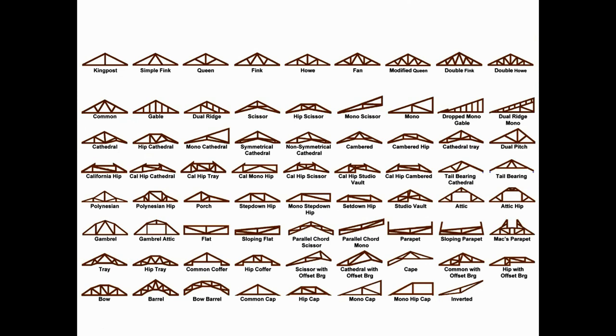And just to confuse you enormously, particularly when it comes to roofs, I should quickly mention that a sloping roof is not a silly thing. You look at buildings and think, oh gosh, a modern building has a flat roof, an old-fashioned building has a sloping roof. Well, there's a lot to be said for sloping roofs, and one of them is that the work of the roof, if you like, in getting rid of rain or snow, whatever else happens to fall on it, gravity is helping. Gravity is doing the job.